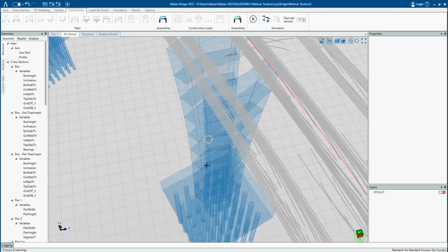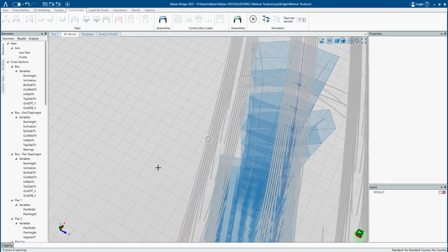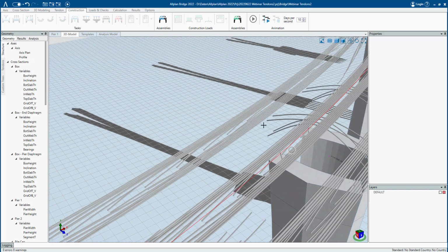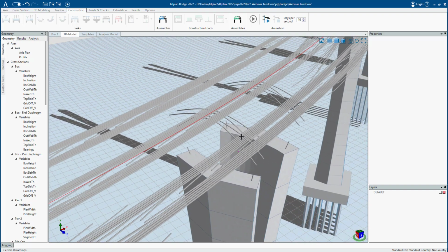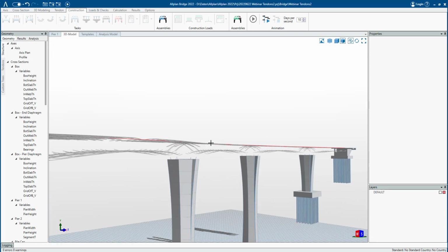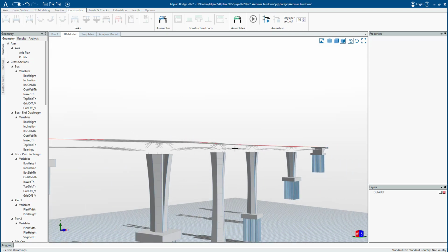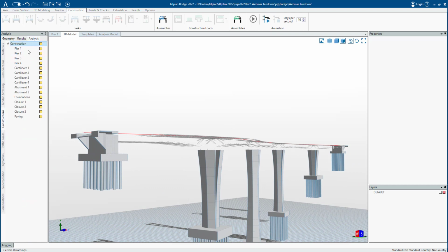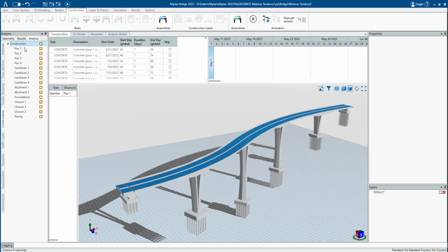And as you can see here from the construction process of the cantilever balance bridge, a lot of tendons are needed for the individual stages to be installed and set. Here you can see them. They are mainly fitted on the top and on the bottom of the girder, but also in the area of the pier it's necessary to have some transversal tendons in place.